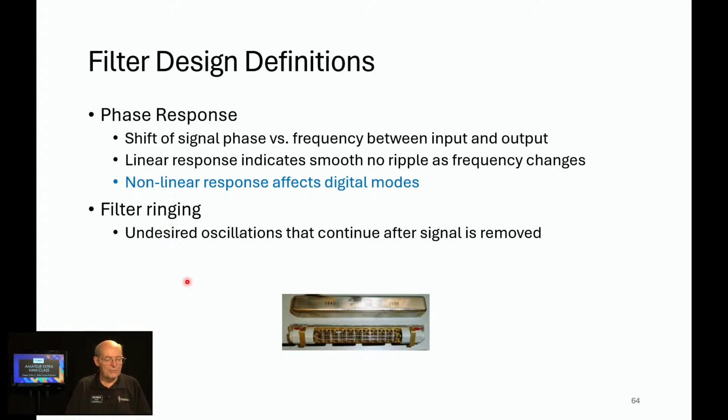Filter ringing is, I don't know if you've ever narrowed a filter in a radio and got narrower and narrower, and sometimes it'll just start ringing. Like listening to CW, the CW elements are there, but the filter wants to oscillate and just keep right on going. That's called ringing. Another analogy would be like tapping a wine glass, and you slowly hear the vibration fade out. So that's something that kind of comes with analog filters.